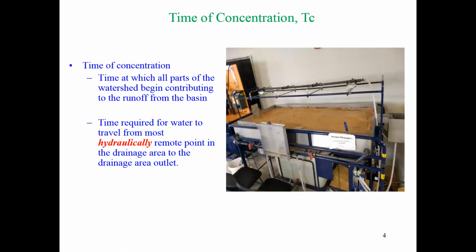So just to remind you, the time of concentration was the time at which all parts of the watershed begin contributing to the runoff from the basin. It's like from each part of this watershed, they will contribute to the flow at this outlet. And we also discussed this time of concentration. It's about time, not about the maximum distance the water is traveling. Rather, it is the maximum time required for water to come into this outlet.